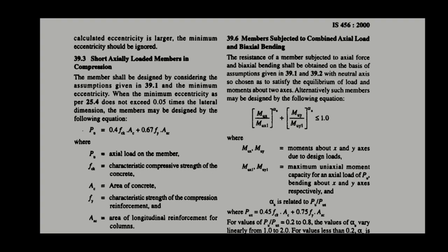That means axially loaded short column. Let's check out the assumption. The member shall be designed by considering the assumptions given in 39.1 and the minimum eccentricity.